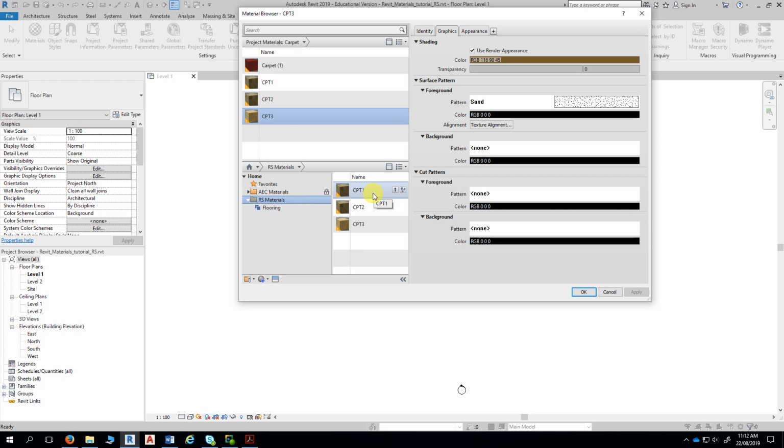Is that changed if the texture maps aren't materials? Yeah, no, the thing is that the texture maps, if you use texture maps, they become an external reference. So they're not embedded in the material itself. They'll always be externally referenced, and that's the issue, really.